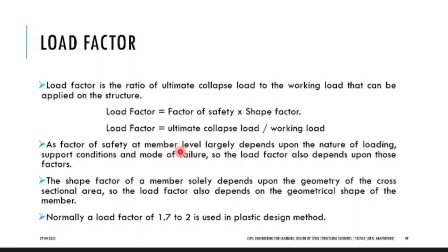It should not break at 11 kilonewton, though 10 kilonewton is elastic. When you are designing any section, the plastic stage should happen only after 2 times of that. If 10 is the elastic limit, the plastic limit should go beyond 20, so that the material will not break immediately, it will last longer.